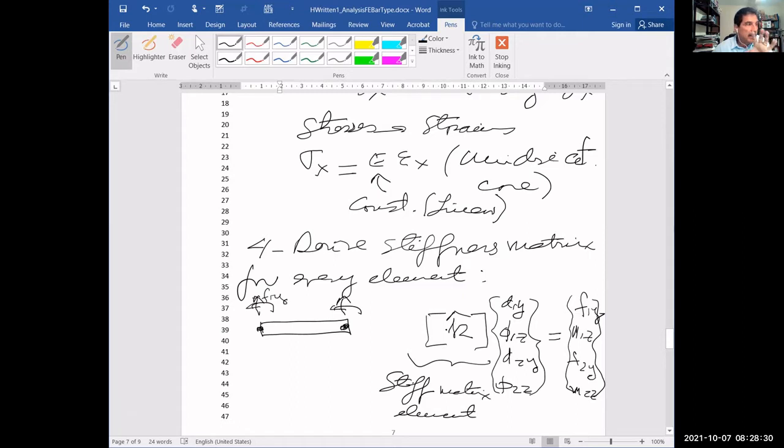In here, you are going to have Young modulus, inertia, length. So these are the unknowns, 4 unknowns. And this is something that we should know. That's the forces on the joints. External. These are external. Don't worry, we will study this in detail in next session. So this matrix is the stiffness matrix. Remember, this is 4 by 4, this is 4 by 1, and the result of that is a vector 4 by 1. Okay?